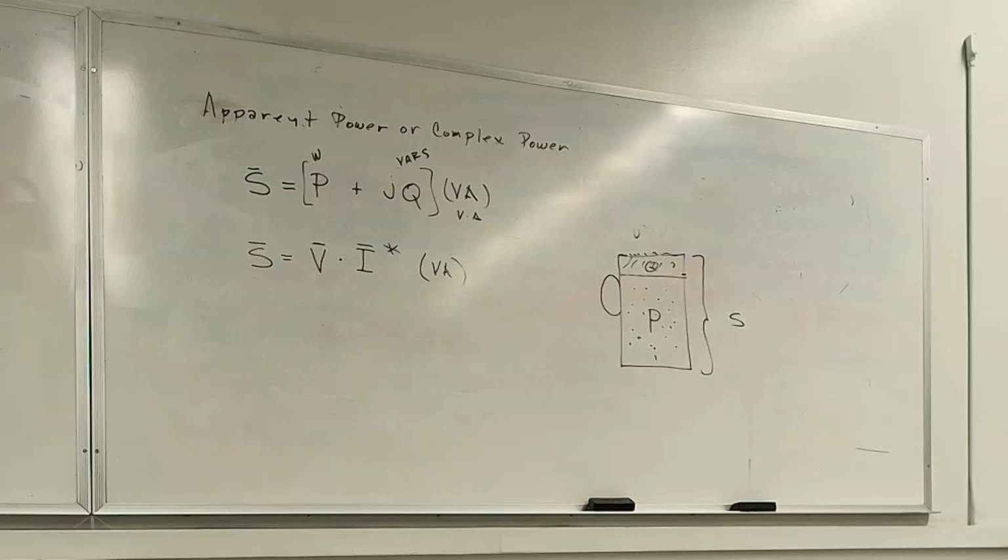So when you have conductors, transformer windings, motor windings, the magnetic field that is produced is the one that is asking you for the vars. They might not do work for you, but without the Q, the imaginary power, your system won't work, because you do need that energy, right?